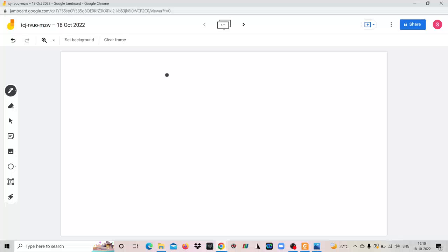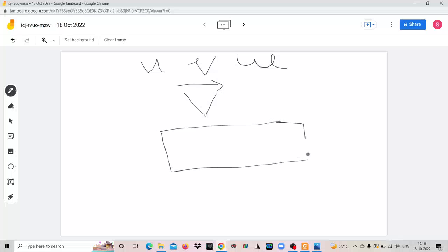One is the component along x-axis, the other one is the component along y-axis, and the third one is the component along z-axis. So we normally represent it by u, v, and w. Okay. So when this velocity is not changing at a particular instant of time from section to section, suppose at a particular time instant, say I'm calling it t1, the velocity at section 1, at section 2, at section 3, the velocity distribution of the velocity field is same, then we call it uniform.